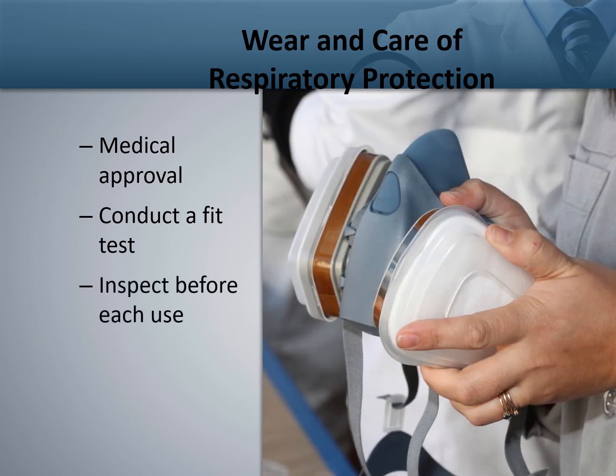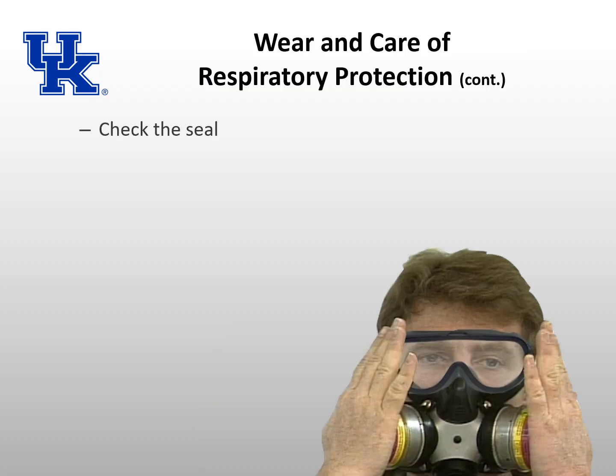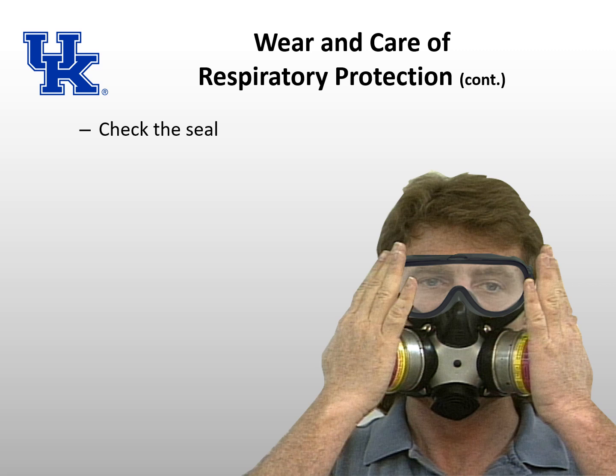Finally, you should always inspect your respirator before each use, checking parts such as the seal, head straps, valves, and cartridges for signs of cracking, wear, or other damage. Any damaged parts should be discarded and replaced. Here are some more steps to follow if you wear a respirator in the workplace.